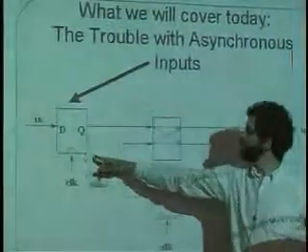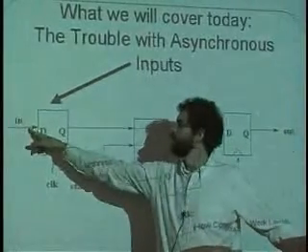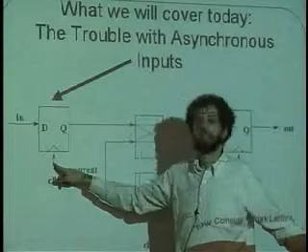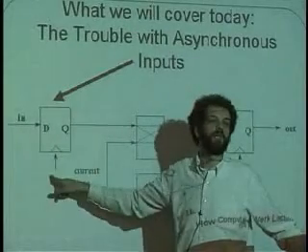You just backed it up a step. I just backed it up a step. That's right. I've just passed the buck to this flip-flop right here, and it may still be the case that the input here will change on this D input during the setup and hold time of the flip-flop with respect to this clock.